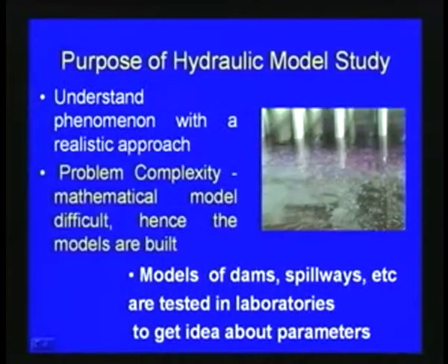As I mentioned, take this particular sump pump model study which we did in our hydraulic laboratory. It is very difficult to mathematically represent the turbulence or the vorticity formation with respect to this heavy amount of pumping.